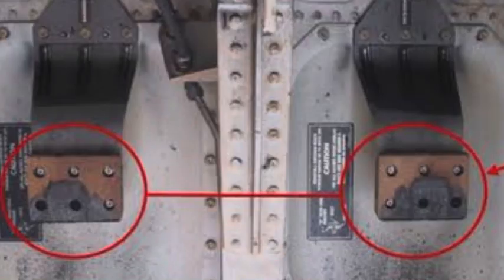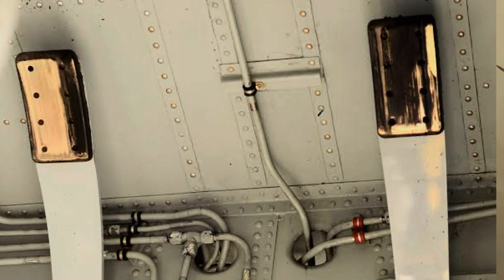Then, since we do not have brakes available in the nose landing gear, after takeoff the nose wheels will continue rotation. So how to stop this rotation? We have two snubbers attached at the ceiling of the nose wheel well, so the nose wheels will attach to the snubbers and the rotation will be stopped.